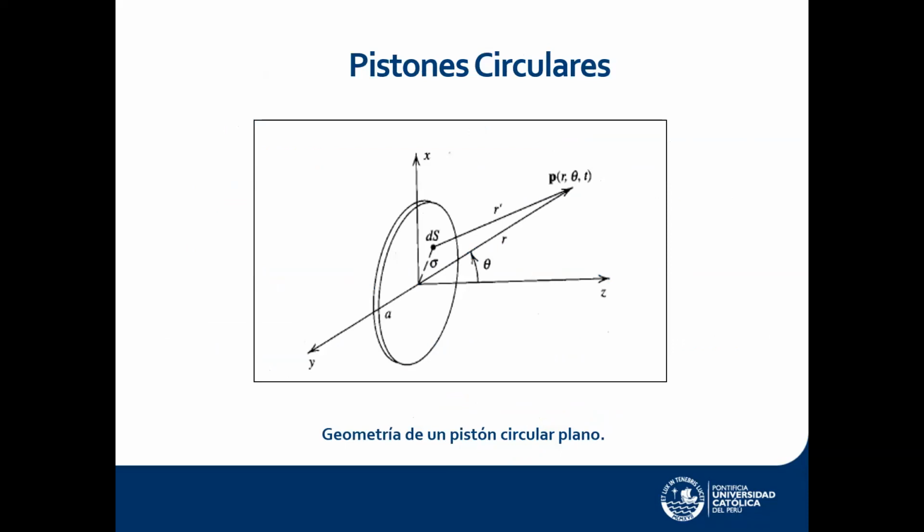So in order to actually do this, we go to some models for acoustic radiation. And one of the ones that you would probably more commonly encounter in the literature is a circular piston. A circular piston is actually a very nice model. It's a very common design for single element transducers. And circular pistons you'll probably very commonly find for non-destructive evaluation of materials.